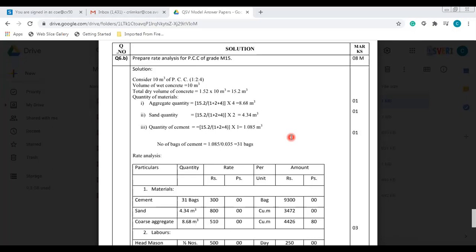So what will be the quantity that you are getting? Can anybody tell me the calculation? 10 feet by 12 feet multiplied by 6 inches. Inches you have to convert into feet. So do the changes accordingly and tell me for a single slab panel how much quantity you require. See, such fast calculations you need to do while working on the site. Because the size is with you.